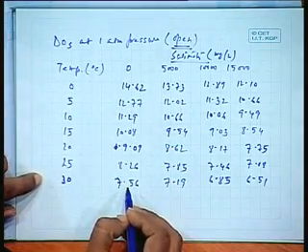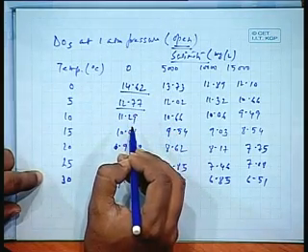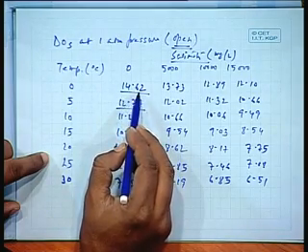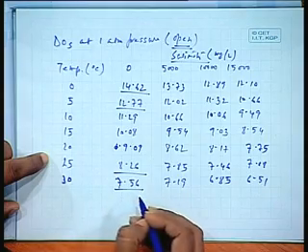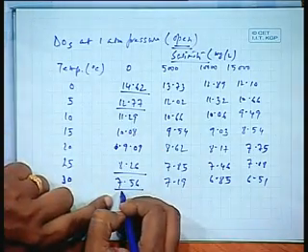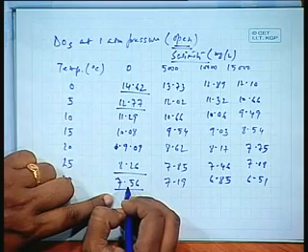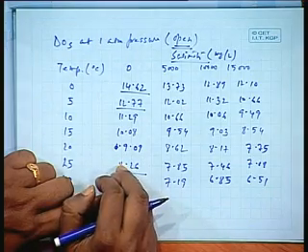See, here it is about 1.5 milligrams per liter change, whereas here it is almost about 0.3. So as such, the depletion increases with temperature, and the rate of depletion decreases. Oxygen gets depleted with higher temperature, but the rate of depletion decreases with higher temperature.